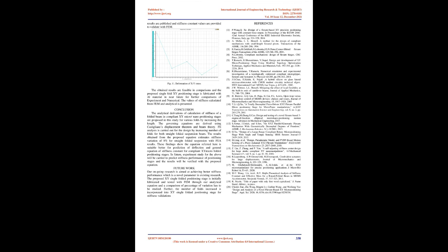Future work. Our ongoing research is aimed at achieving better stiffness performance, which is a novel parameter in existing research. The proposed XY single-folded positioning stage is initially fabricated and tested with FEM through our analytical equation, and a comparison of percentage of variation has to be studied. Further, an increased number of folds is incorporated into the XY single-folded positioning stage for stiffness validation.